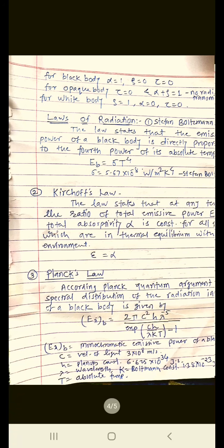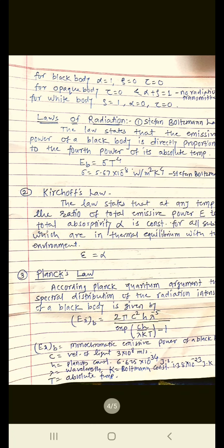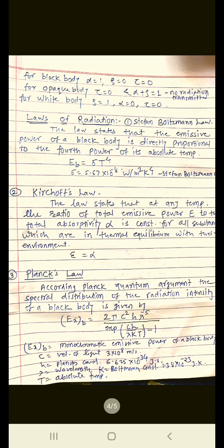Second, Kirchhoff's law. The law states that at any temperature, the ratio of total emissive power E to the total absorptivity alpha is constant for all substances which are in thermal equilibrium with their environment. That is, epsilon is equal to alpha.